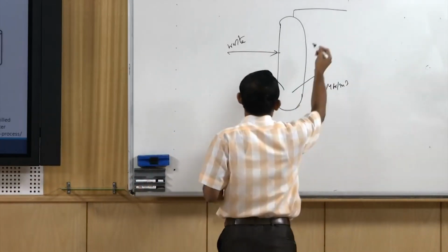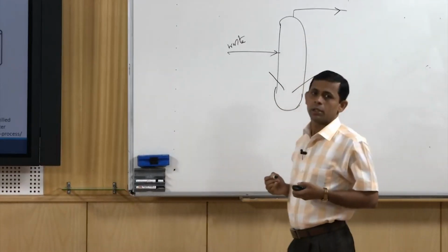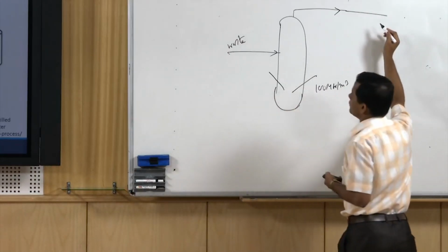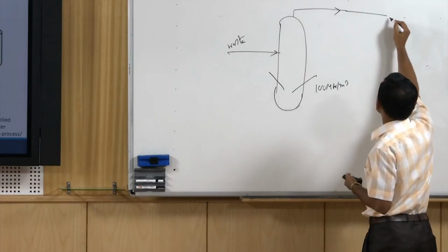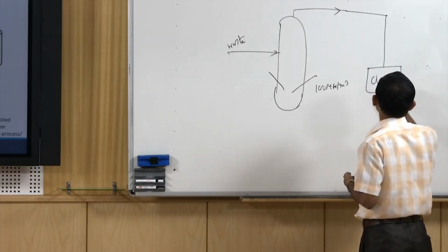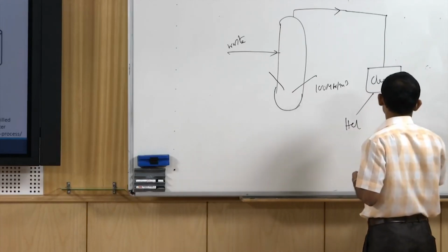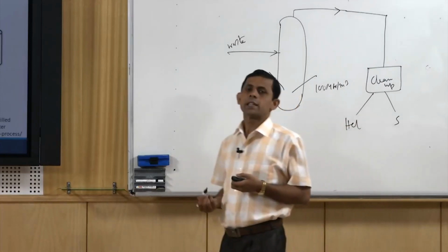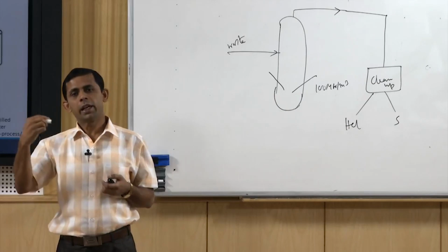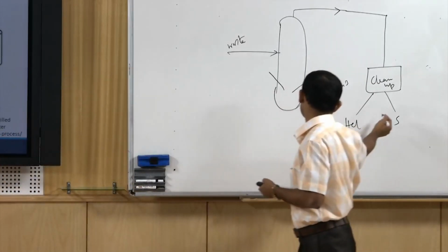So when the syngas cleaning and conditioning concept comes, through syngas cleanup we will get HCl, we will get sulfur. Unlike other gasifiers where we get acid gases like H2S and again convert this H2S to elemental sulfur, here this conversion takes place directly.